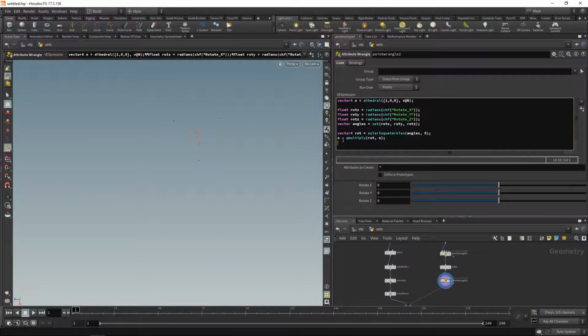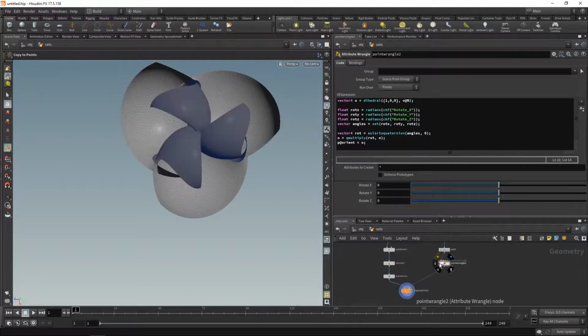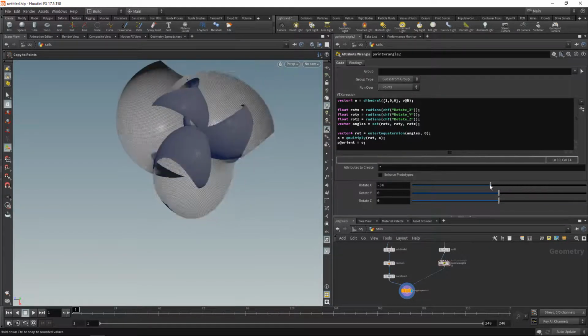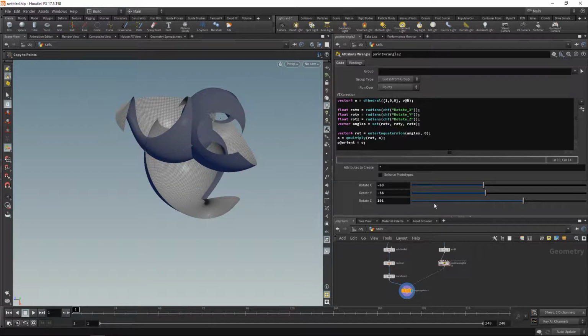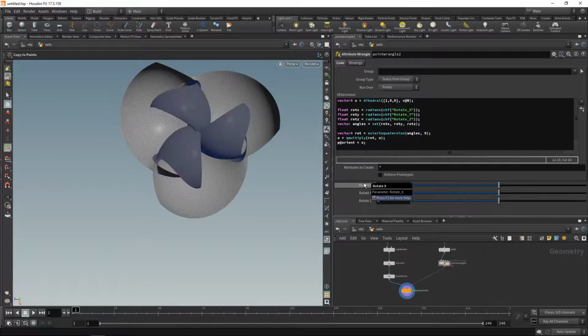And finally, I'm going to write out our O value to a vector 4 called orient. Like this. Let's keep our fingers crossed. Highlight this before and after so we can see there's something happening, and let's try rotating this. So yeah, that's working too. And there are easier methods or other methods of doing this, but using a quaternion is not the easiest, but a rather safe way of orienting copies and instances in Houdini using the copy to points.